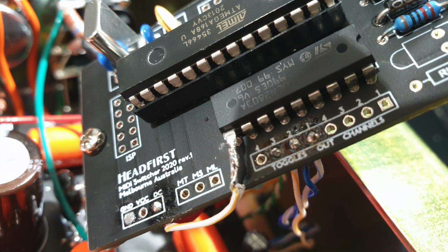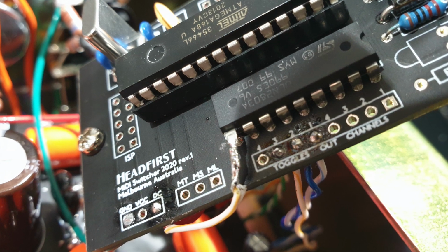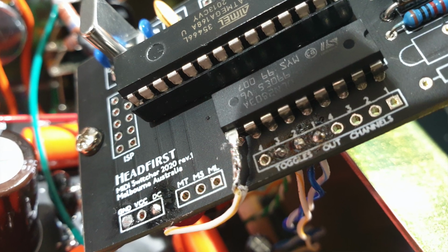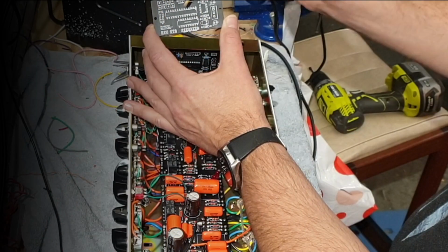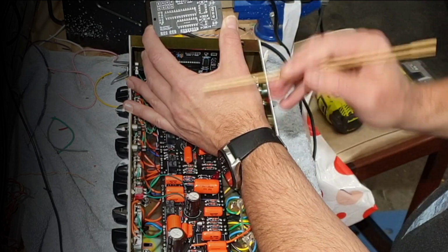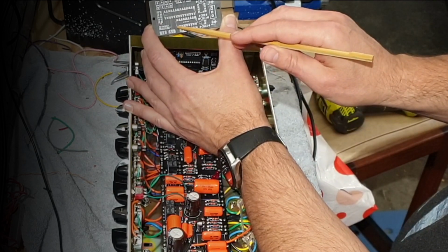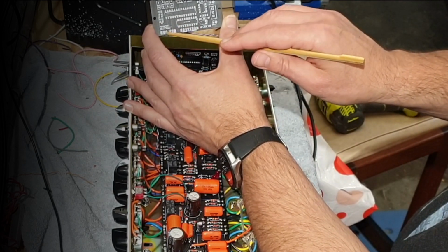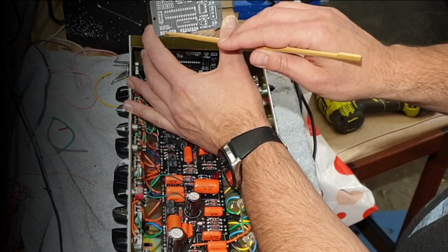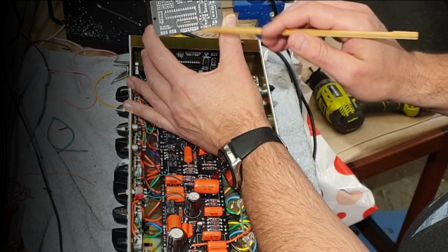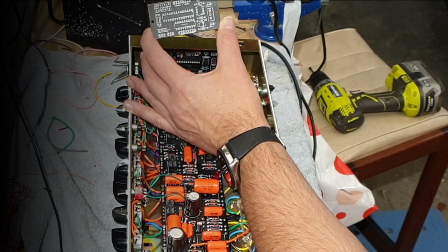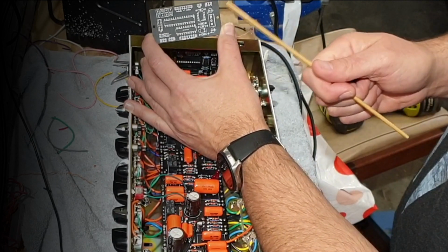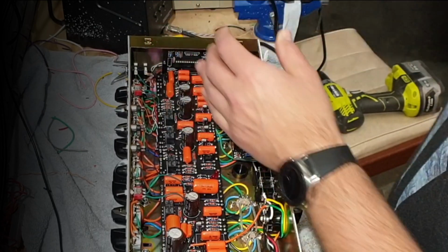And you've got 12 volts on this board because it's coming in on the DC input here or over here, whichever one you're using. They're both connected. And you can see by lifting that pin out and connecting it to DC, you're now running the NPN array chip at 12 volts. It will be able to switch your relays back and forward, no problem.